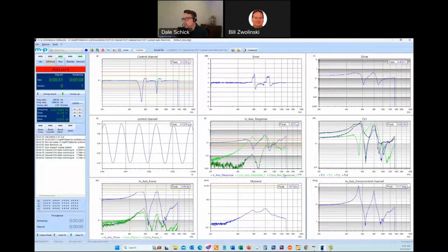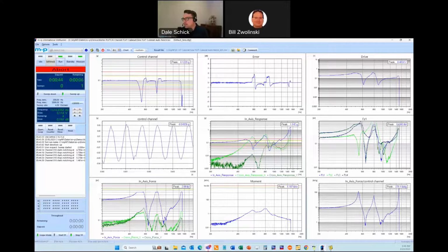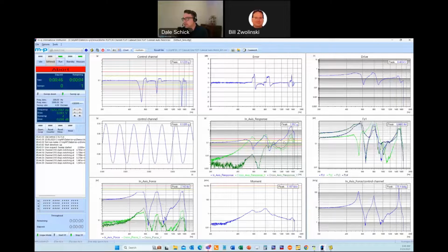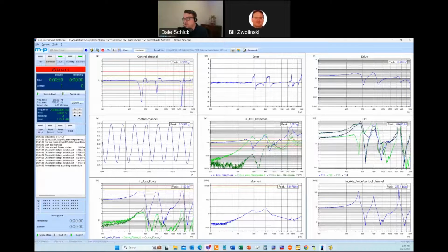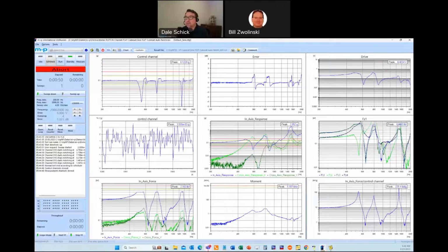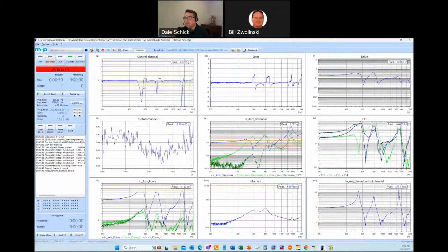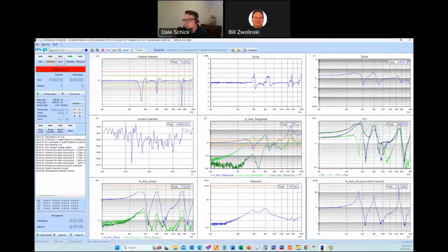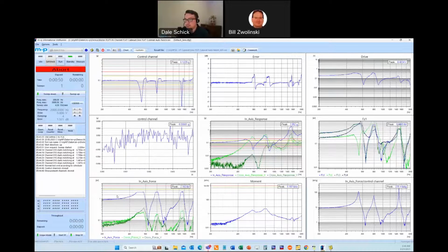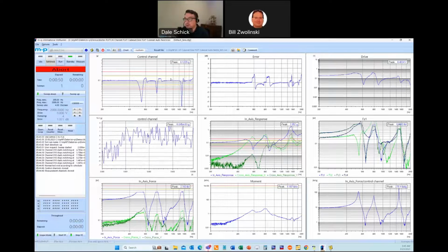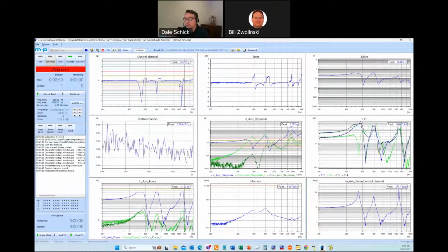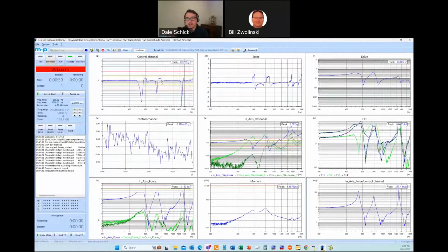You can see my cross-axis response here. Here's the cross-axis X in light green and the cross-axis Y in green. And these cross-axis responses toward the mode do get close to the input profile as far as the 0.1 Gs is concerned. Now notice this test, because I drew this manual notch, or this automatic notch rather, all the way across the in-axis force, it predicted and accounted for the third mode. And even though my analysis was poor and I didn't predict it, this automatic notch did.